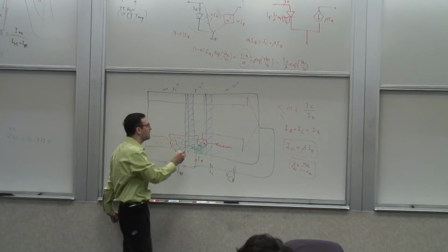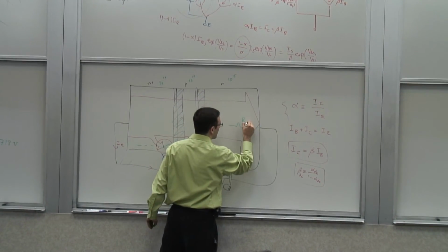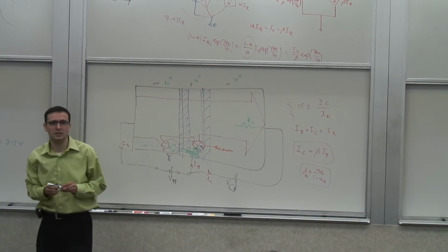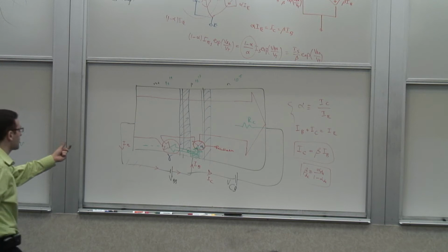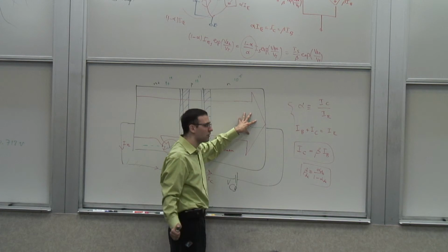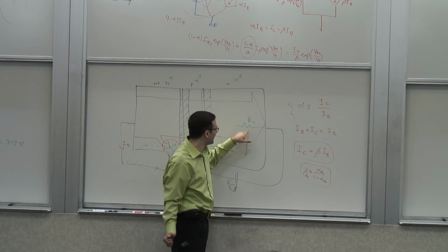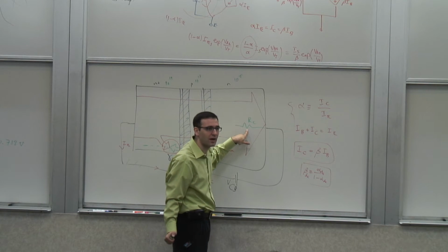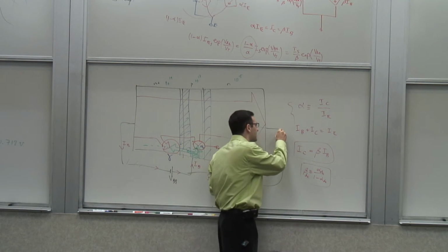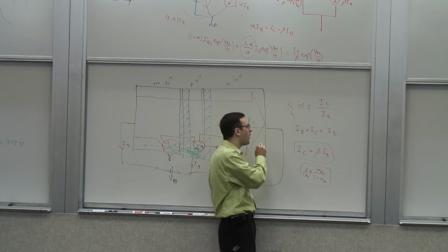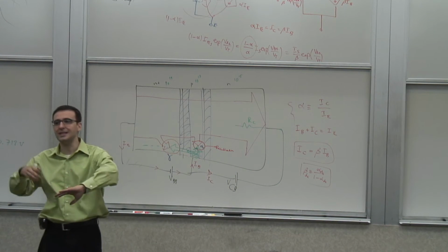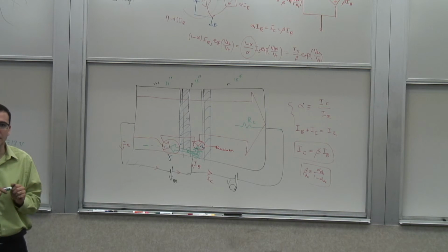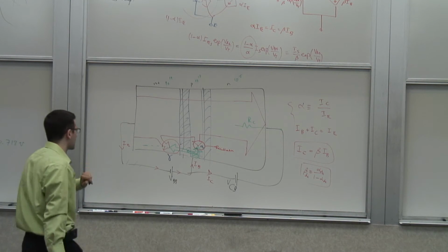So I have a reasonably large series resistance, RC, here in the collector. Which is not a good thing, because that's where most of my current goes. So if I have a large RC, then I'll have a reasonably large voltage drop across here. But this is intrinsic, internal to the device, so the voltage I can actually see and use is here. I don't want to lose a lot of my voltage swing inside the transistor. In addition, it generates heat and all sorts of things, right? So I want to minimize its resistance.